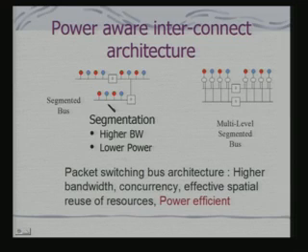Now, this also saves power, it uses lower power. Why? Because if I have a single level bus which has to operate at a higher clock frequency, that means there will be more consumption of power. But many of the devices cannot operate at that frequency, it will introduce wait cycles. During that period, the consumption of power is, in a sense, a wastage. So, if I have buses operating at two different frequencies, two different speeds suited to the devices, then the power consumption becomes different. It is not the same for the entire bus onto which the devices are connected.